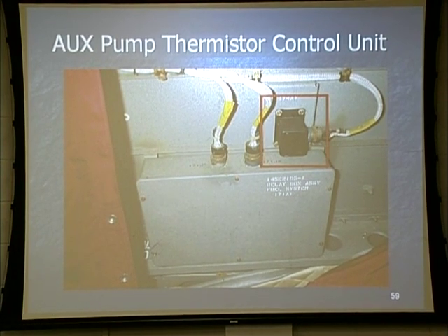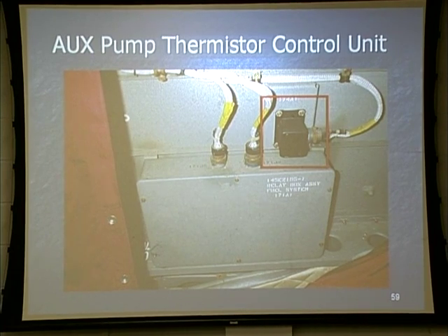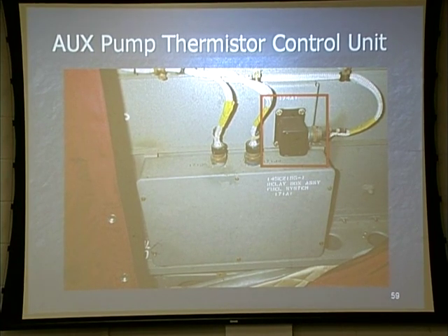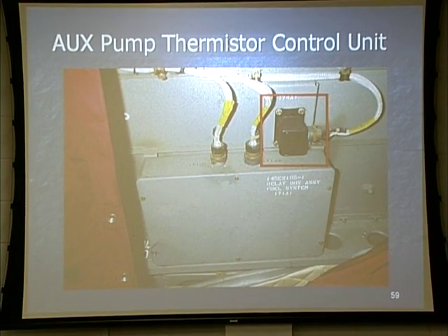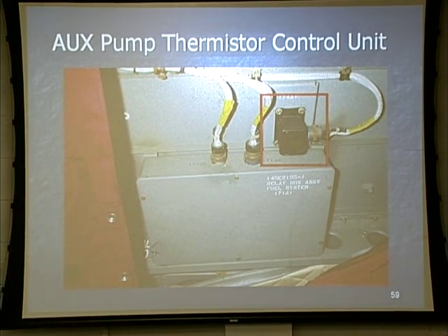At the top you got your aux pump thermistor control. Why? Because in order to turn on the aux pumps, it has to check those thermistors first, which makes sense, right? If those thermistors are not covered, then it's not going to turn that pump on.